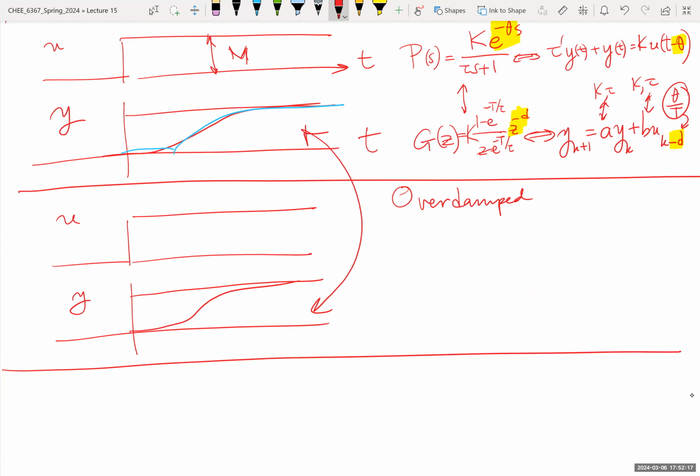Of course, you could approximate this by trial and error using a pure second order response. That is certainly doable. Or you could use formulas in textbook sheets. I don't even recommend that because it's not worth going through that level of detail. Simple idea, use first order plus time delay, or use simulations for second order. Trial and error will give you a good response. It's good enough. That's what I'm suggesting in the notes.